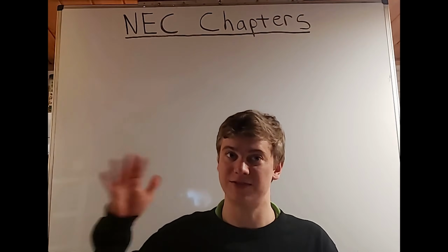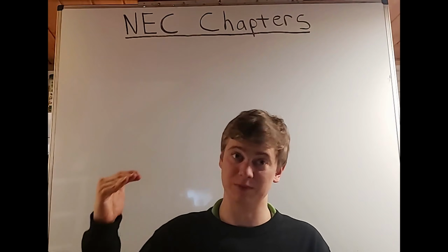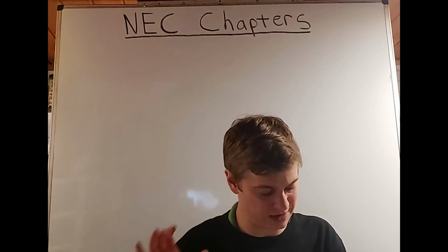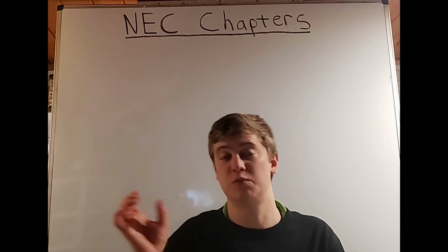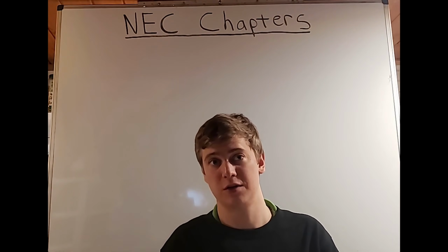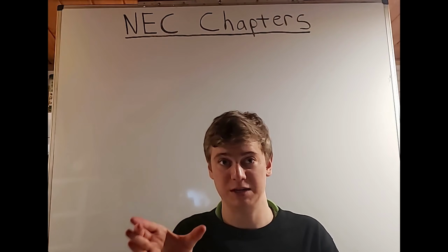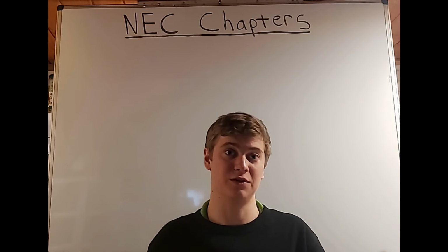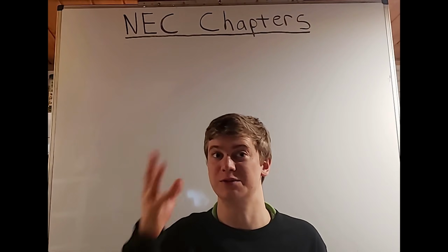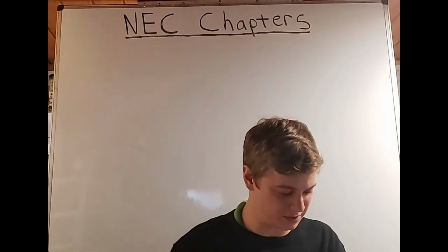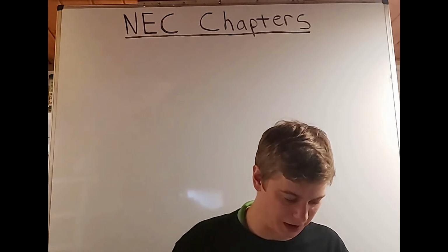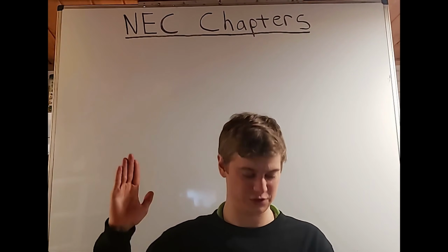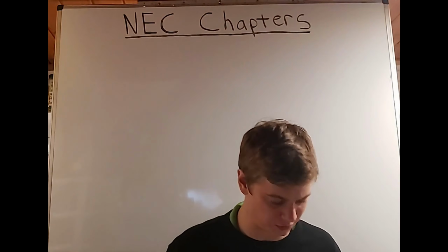Okay, so when they're talking about the height, they're saying that it has a minimum of 6.5 feet. It can be taller. And then for the width, you have a 3 foot wide, or the width of the equipment, whichever one is greater. Okay, so you have to have a 3 foot minimum, and then you're only going to make it a bigger width if your equipment is bigger than 3 feet. Okay, so there's some nuance there. And then it talks about the depth being required in 110.34a, and in all cases, the working space shall be permitted to have that 90-degree opening of doors or hinged panels.